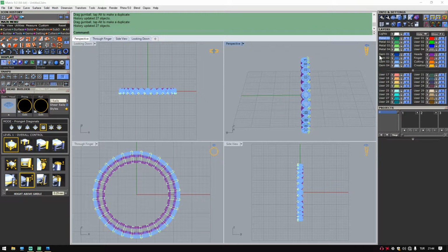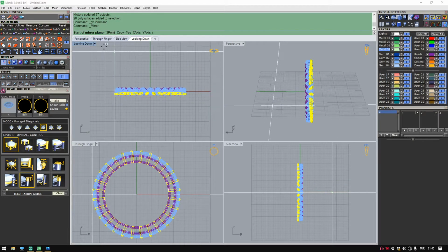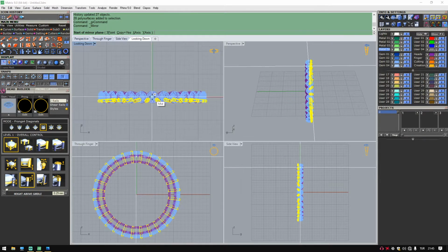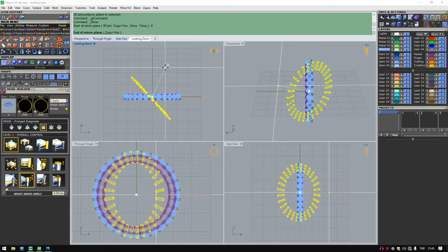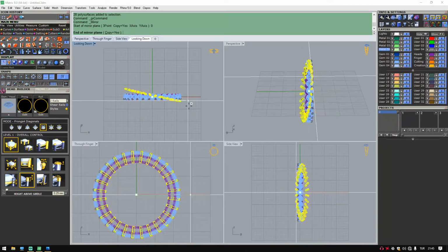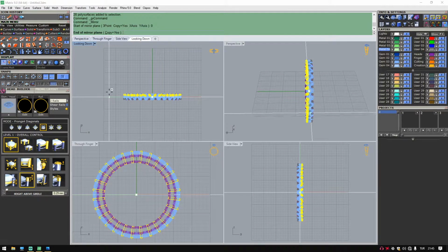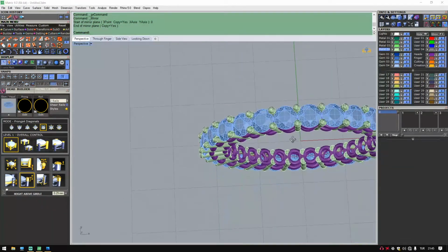Those are all green, all metal 04. And if I right click with my mouse, right here, now I can go on this menu, hit Mirror, and it's asking for the start of the mirror plane, which is going to be this 0 here, the center of our construction plane. 0, enter, and now as you can see it's mirroring to the other side. It's working in a mirror dimension thing. If you press and hold Shift on your keyboard, it will just stick at 90 degrees. Now as you can see we have better prongs.